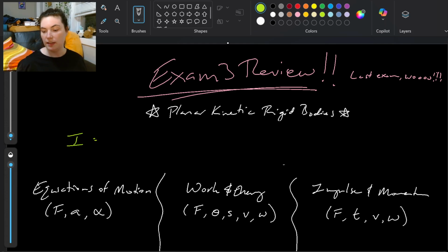Right, so one that comes up pretty frequently is when we're given that radius of gyration. So when you have that radius of gyration, that k value, you can use mk squared. And so that was a really nice one to kind of shortcut us from having to look anything up. Right, so we can have radius of gyration gives us moment of inertia. Otherwise, we generally look up our IG, our moment of inertia about that center of mass, from our tables.